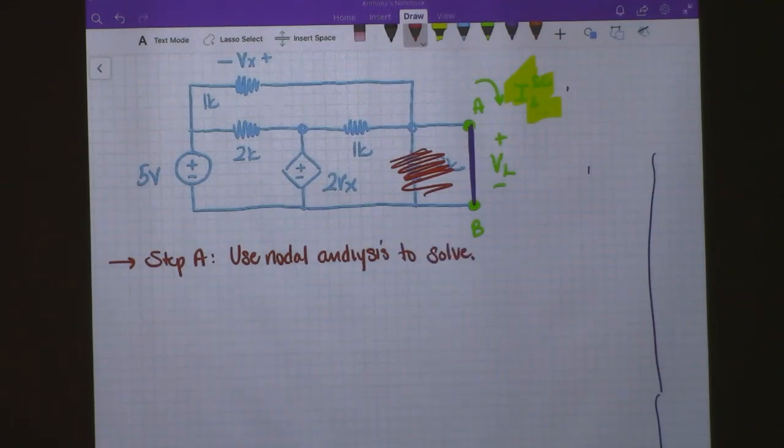All right. So how many nodes do we have? I'm going to fly through this because I'm hoping by now that everybody's pretty well adept at this. Remember what I said about the midterm. If you're still having issues with the nodal analysis or the mesh analysis, you really need to go back and take a look at it. Yes? Are we not counting the 2 K ohm resistor anymore? Yeah, that's shorted out, so that's not going to have any effect.